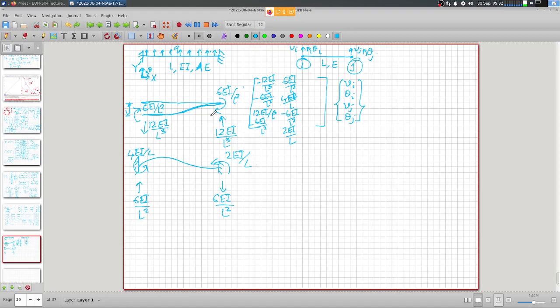Just look at the forces correctly. Maybe I got the senses of the forces wrong. But the idea is, when you have this element, you already know its stiffness matrix. We already demonstrated that the stiffness matrix of the beam element is the same as what you obtain from the stiffness in the matrix methods of analysis. So that was settled, and you could have straight away started from this point that the beam element would be a C1 element of two nodes with 2 degrees of freedom at each node, Vi theta I and Vj theta j.